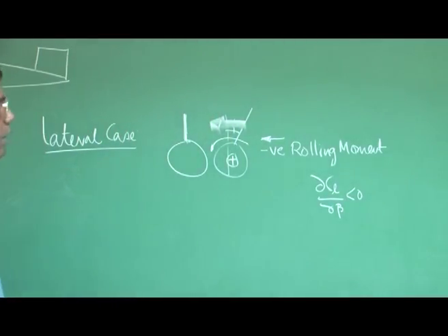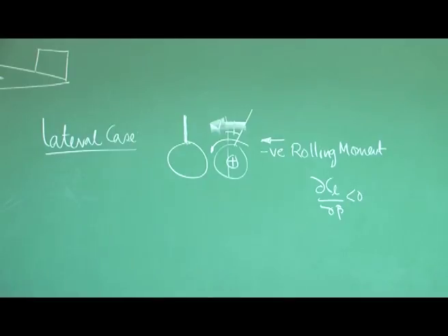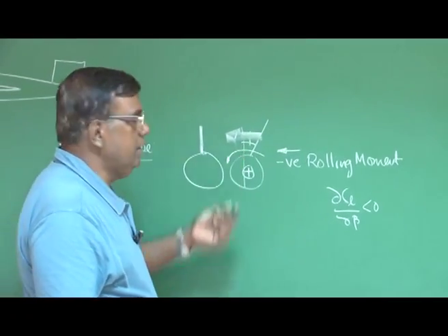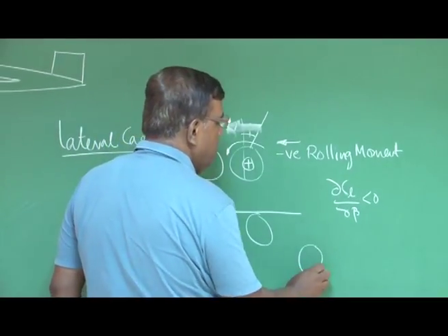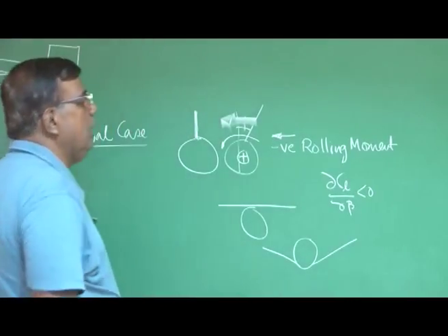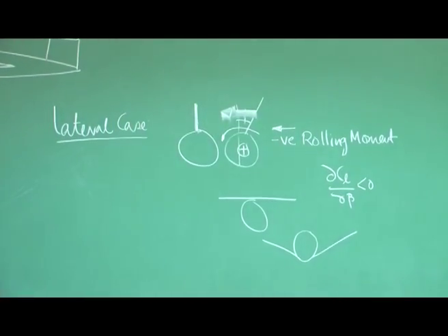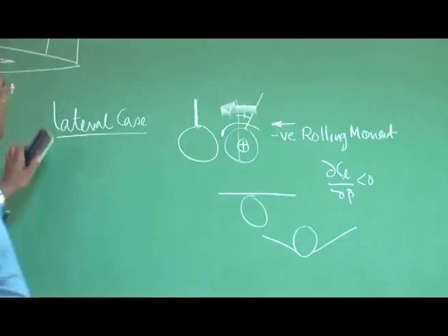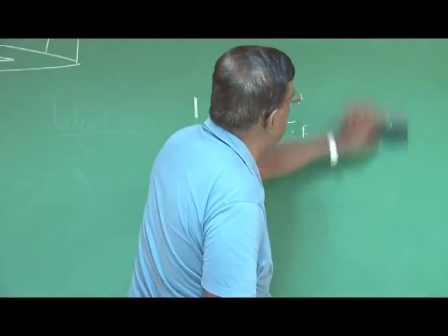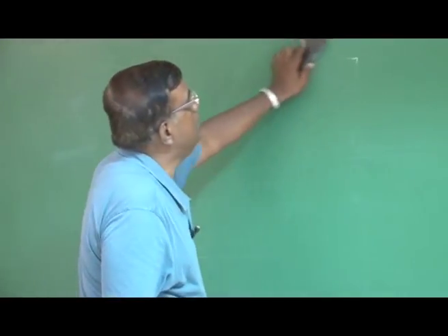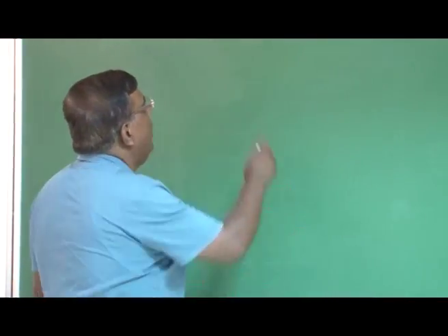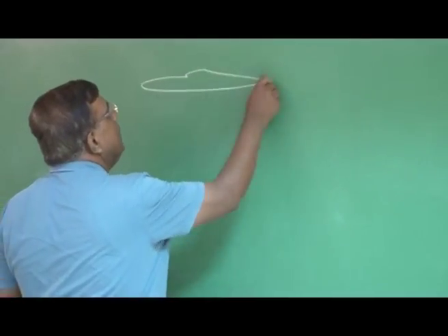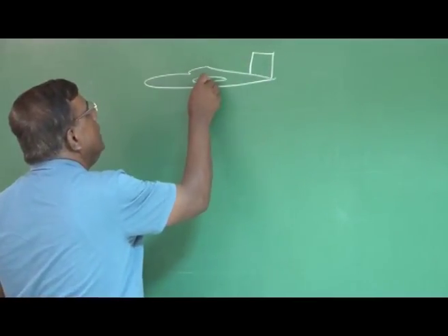We have seen that I can have lateral stability through a vertical fin or vertical tail. Also, we can have it through a high wing as well as by giving a dihedral. All these things we have covered in the earlier course. I just thought I would revisit this. Now, we are talking about dynamic stability, we are talking about the transient. So, it is important that we understand what forces and moments we will be primarily concerned with.